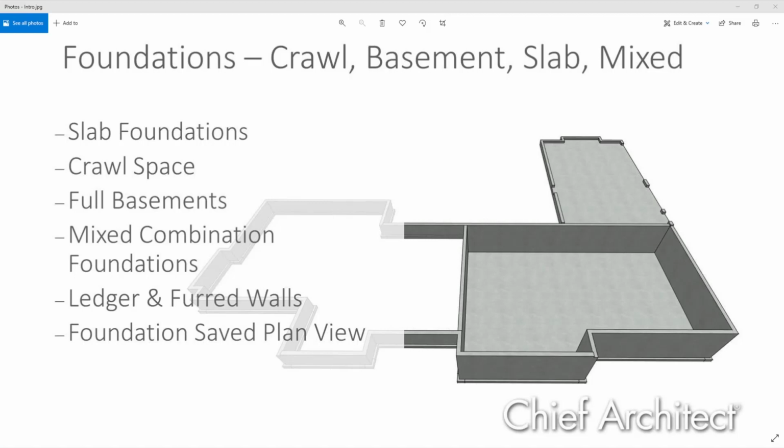And as soon as I go to build foundations, the program gets really upset that the floor for the garage is 28 inches lower than the house. So it takes that stem wall, even though I don't have that, I have a slab for the garage, and it ends up throwing this stem wall on top of the slab foundation for the garage.